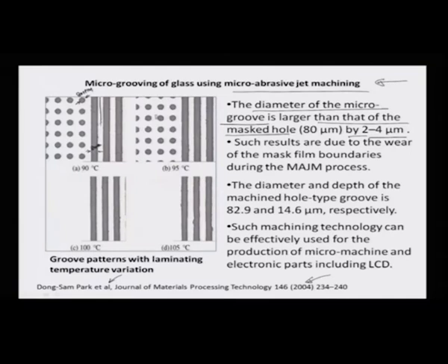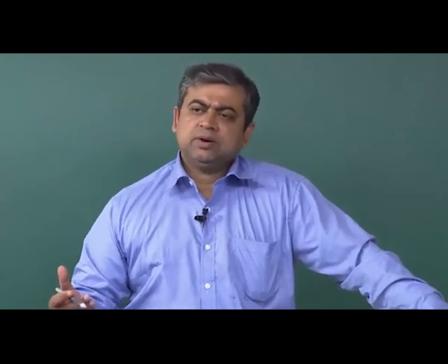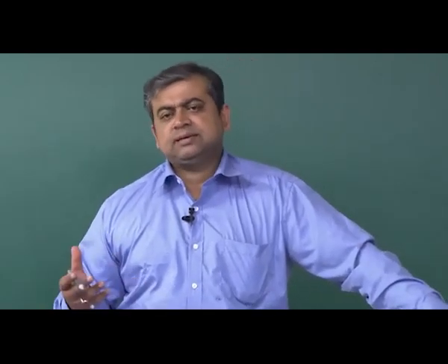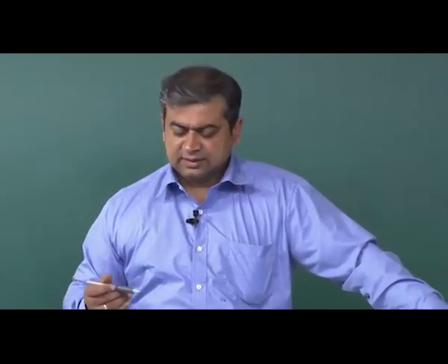And this is of course the depth of the micro hole we're talking about. It's on a different scale. So this has been carved on such a surface using the technique that was illustrated before, that lamination technique. We can see that the masked holes here are typically 2 to 4 microns larger in diameter, probably because in this case the mask was a polymeric mask, as you saw in the last step. There was a lamination issue involved, and because of that the change of dimensions of the polymeric mask would be reflected in the change of dimensions of the surface concerned.